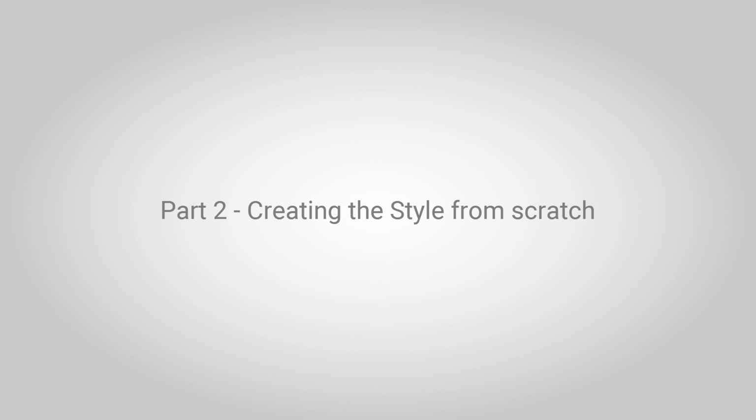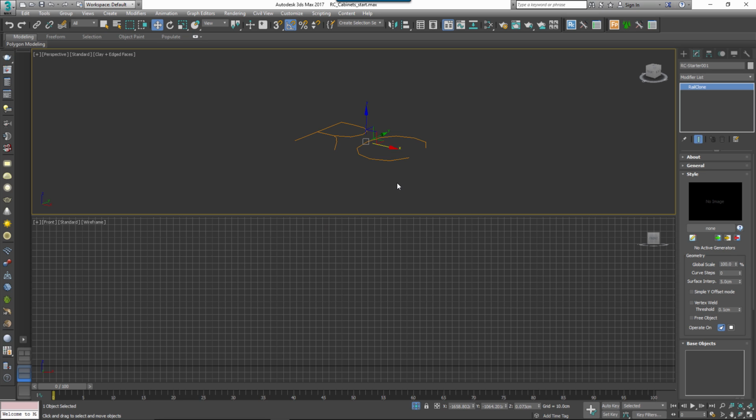The focus here is on the creation of several different but interconnected generators to create a style that adapts to the segments and base objects added to it. Also, almost all of the dimension values are extracted automatically from the segments, so that the style can be really easily updated, either using parameters or by adding new geometry as we've seen. We'll start at the bottom with the plinth.